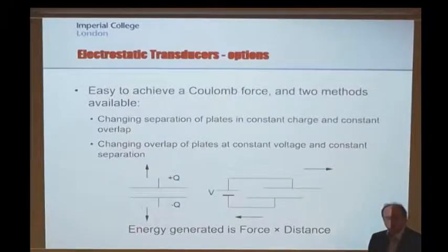is constant. It does not matter about the relative position between the plates, it doesn't matter about the velocity with which the plates are moving apart, you have a constant force. So actually it looks like what we would call Coulomb friction. If you put something on a table and you push it along the table, you've basically got a constant force retarding the movement. Very different to air damping.